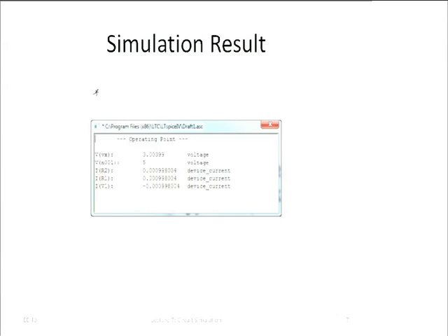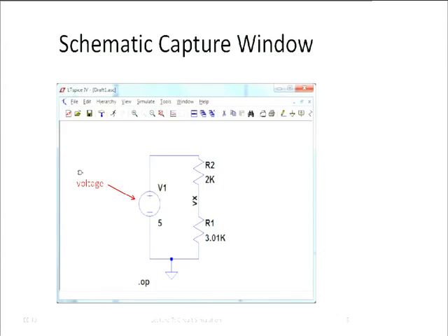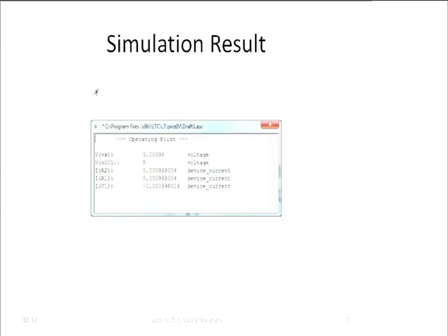There is a node here Vx, and I found a way, also clicking one of these buttons, to call this one actually Vx. Okay. And the node at top there, I didn't give it a name. Then SPICE invents one. Okay? So now we have really three nodes, two nodes of interest, aside from the common node. So the one node is Vx, and it tells you what the voltage is there. And then there is this other node that I haven't given a name.